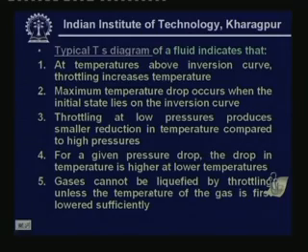So in the liquefaction plants, what is done is the pressure of the gas is increased first, and then its temperature has to be reduced sufficiently so that when you throttle it, its exit temperature is such that the exit condition lies in the two-phase region and liquid is produced. Okay.